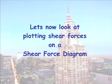I have got my overheads, I realise, in the wrong order here, so I'll repeat this again. What you have to realise is moment is directly proportional to curvature. So when I apply a load over here, my beam is curving different amounts. So that means the value of my bending moment varies. If I cut it at 1 metre, 2 metre, 3 metre, 4 metre, 5 metres, I'll get all these different values for my moment. So what I need now is I need to draw a bending moment diagram.